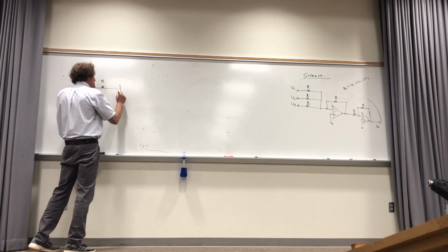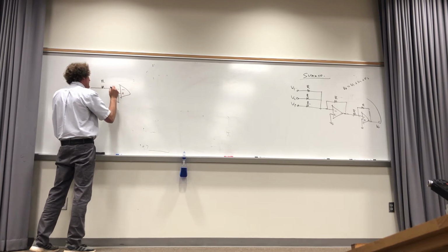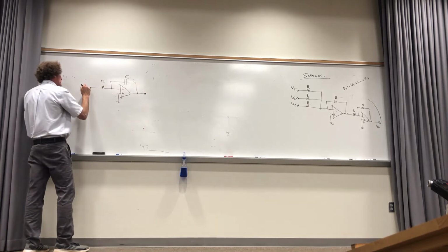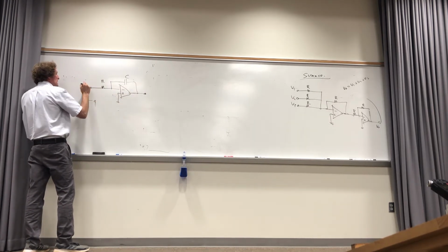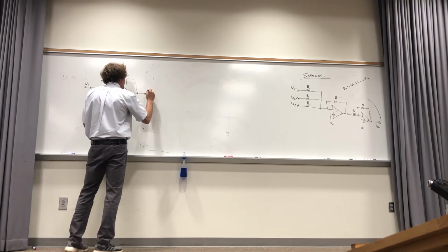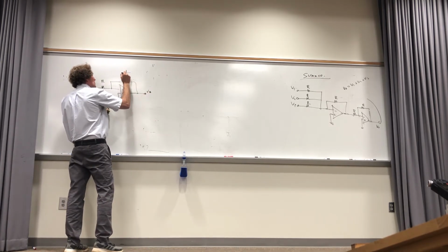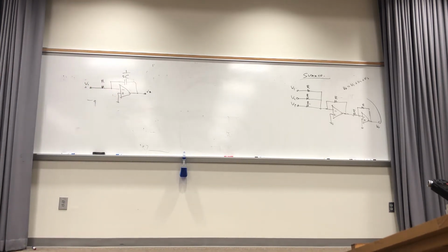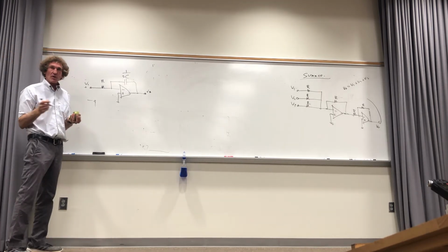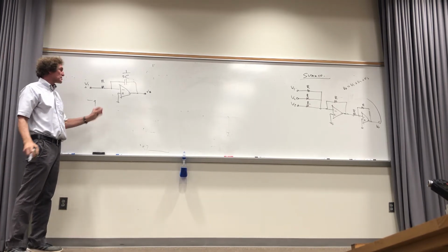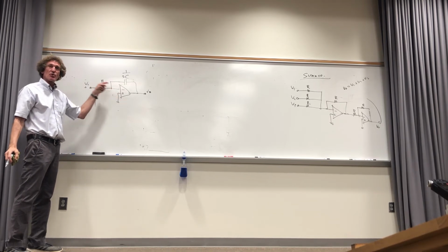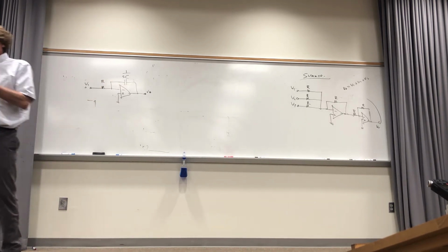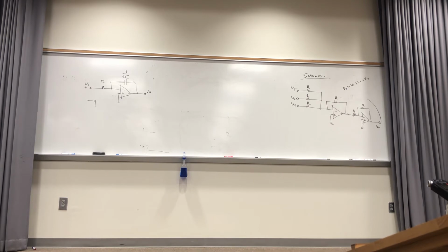This is a simple circuit, really called an integrator. So this is my input and this is my output, right? The impedance of this is 1 over SC, right? Now this is the one in the last test. A lot of people memorized the formula and forgot about the fundamental way an op-amp works. Remember, the way an operational amplifier always works is there's no voltage difference between these terminals and no current into it. So if you get a question with an op-amp where you have to do analysis, always remember that. Don't default to formulas. All right? Be careful about that.